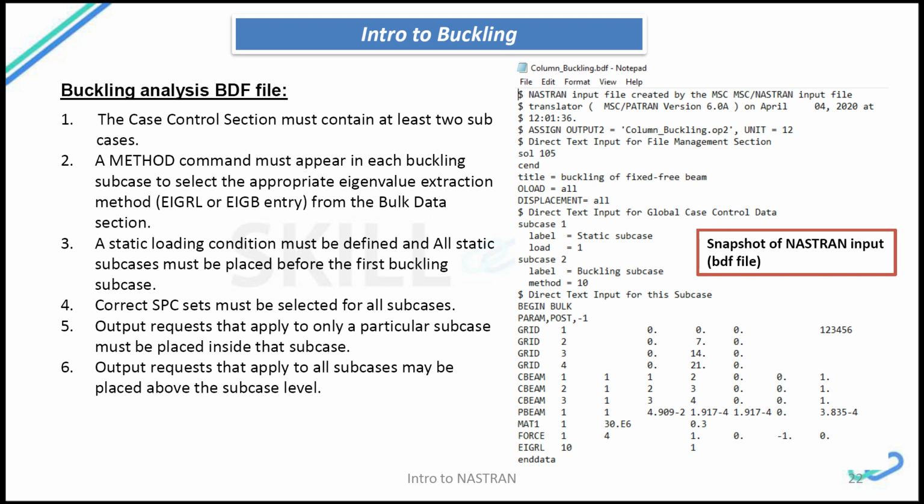Usually Lanczos method is very famous in extracting the eigenvalues. It is one of the methods that the Nastran solver uses to solve the problem. And then a static loading condition must be defined, and all static subcases must be placed before the buckling subcase. Yes, and this static subcase is placed before this buckling subcase.